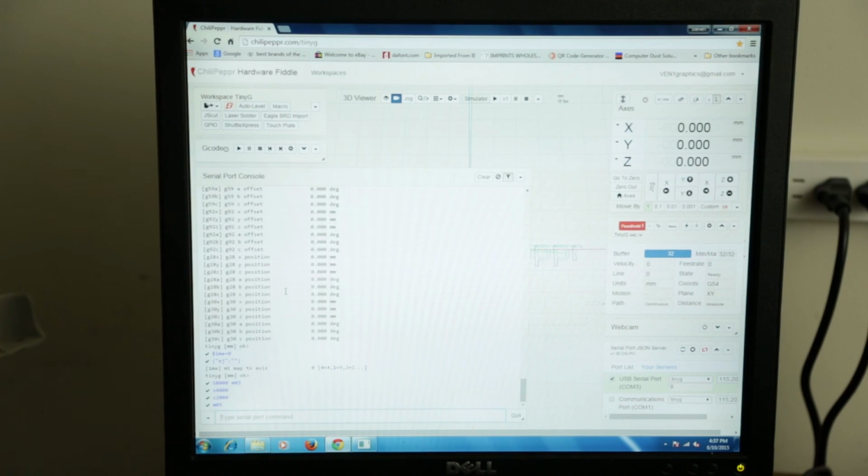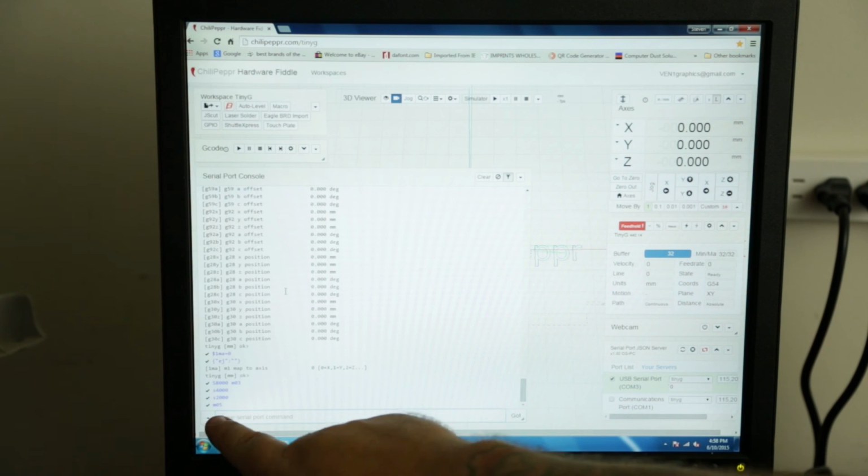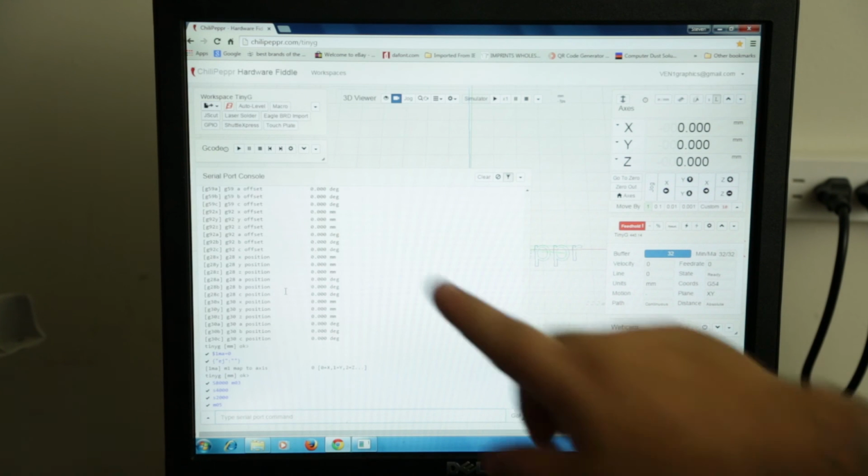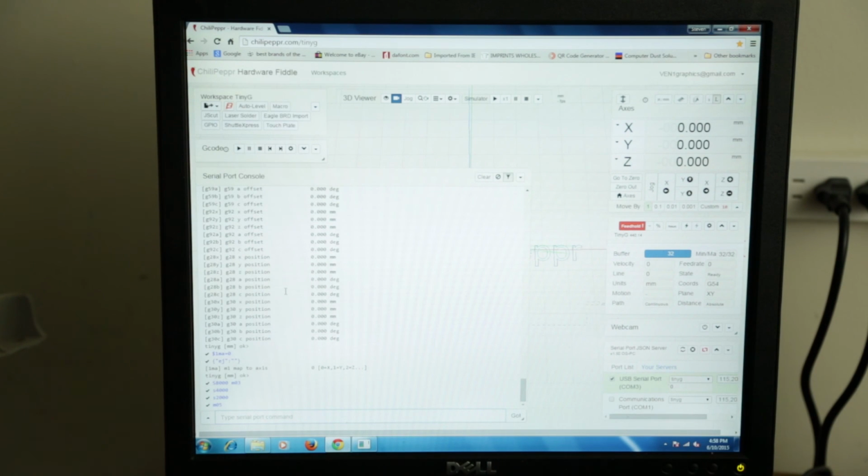So if you don't want to program G-code to turn on your spindle, like if you're using CamBam or JScut and it doesn't turn the spindle on, or you don't put that code in, you can do it in Notepad if you want. You can put this code in wherever you want, and it goes line by line. It does exactly what it says to do. So at the beginning of your cut routine, you type S8000 space M03, spindle will come on, it'll run the G-code, and when it's completed, you type M05, it shuts the spindle off, and you're good to go. If not, before you push play on your G-code up here, just type S8000 space M03, turn it on, push play, and then use M05 to shut it off when the job's over, okay?